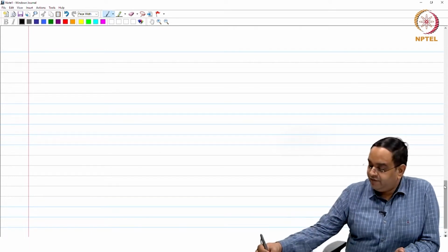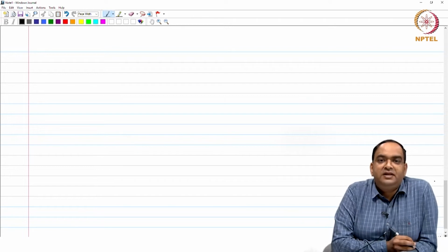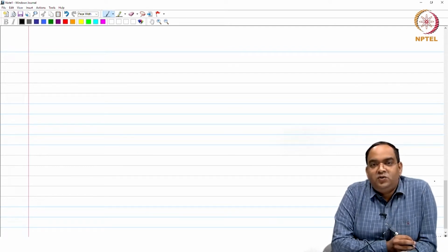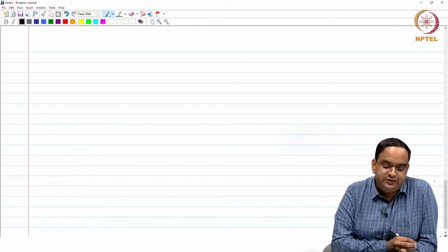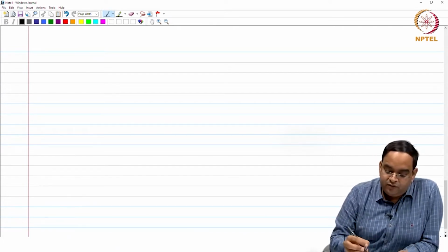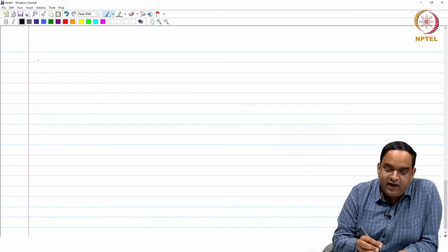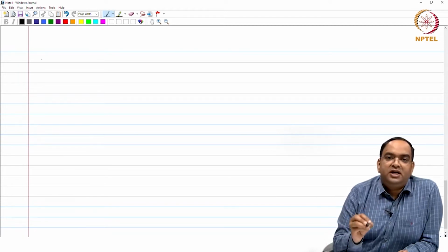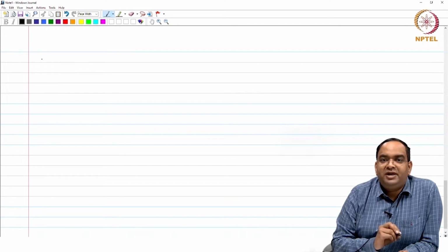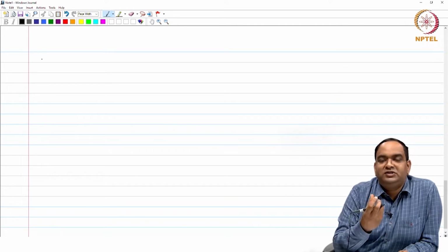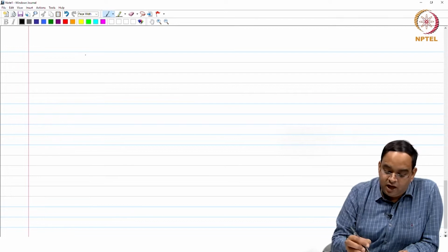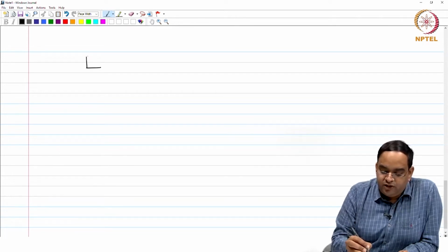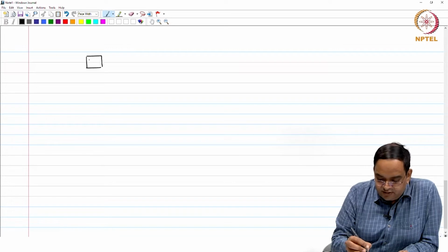So, after identifying the basic noise components in the PLL, we need to do the noise analysis to find out how noise from different PLL blocks add to the output noise. For that, we first identify all the noise sources in the PLL. So far we have found the basic noise sources like resistors and transistors. Now we are going to find the noise of each block.